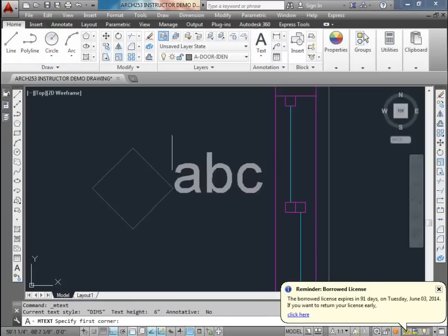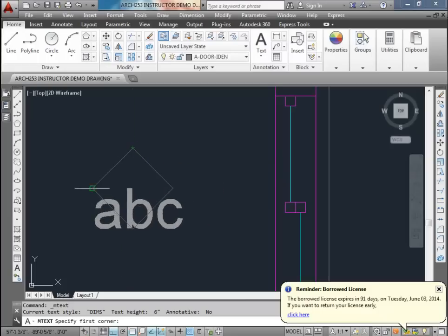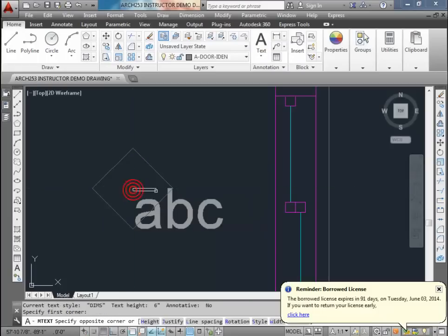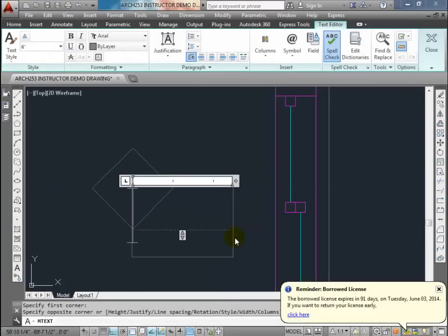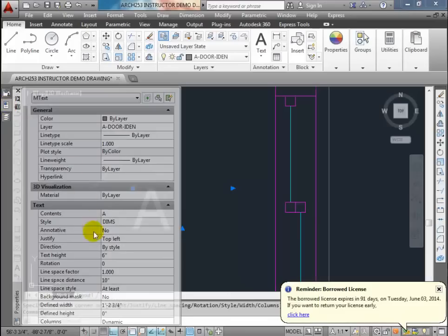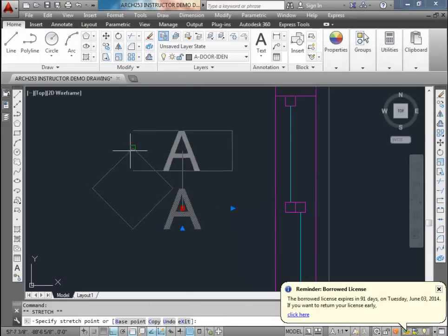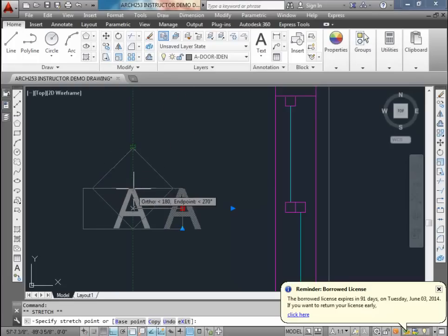And in order to save time, again, you probably want to create this as a block within your window block, so it'll make it a little bit easier for updating later. And these are going to be letters. So for the windows, we're actually going to be using letters, not numbers. So the doors have numbers, the windows have letters, and that'll just make it a little easier for us to organize and keep them separated.